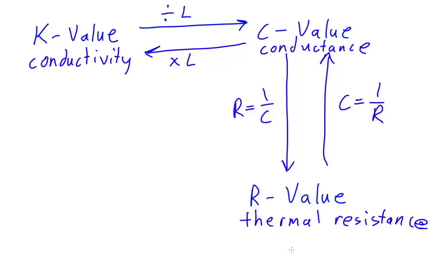Sometimes though, R values can be quoted in imperial units. So the imperial units, rather than using energy in joules, they have what is called the BTU, which stands for British Thermal Units. If you see this and you need to convert it, just so you know, a British thermal unit is 1055 joules. So that's the conversion factor. But the problem is, if you see these British thermal units, you're probably going to be in Fahrenheit, and you might be using per square foot and this sort of thing. So you just need to be really careful with your units if you're looking up values online.